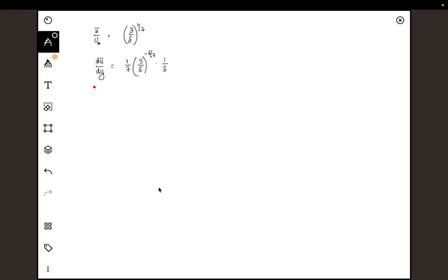So what happens at y equal to 0? It will just go to infinity, right? So does this mean the shear stress is infinity? So we cannot directly use the equation. We cannot directly use the forms that we were using when we were solving the laminar boundary layer flow. So this is exactly why we would need another equation, and that equation comes from a universal velocity profile, turbulent velocity profile.